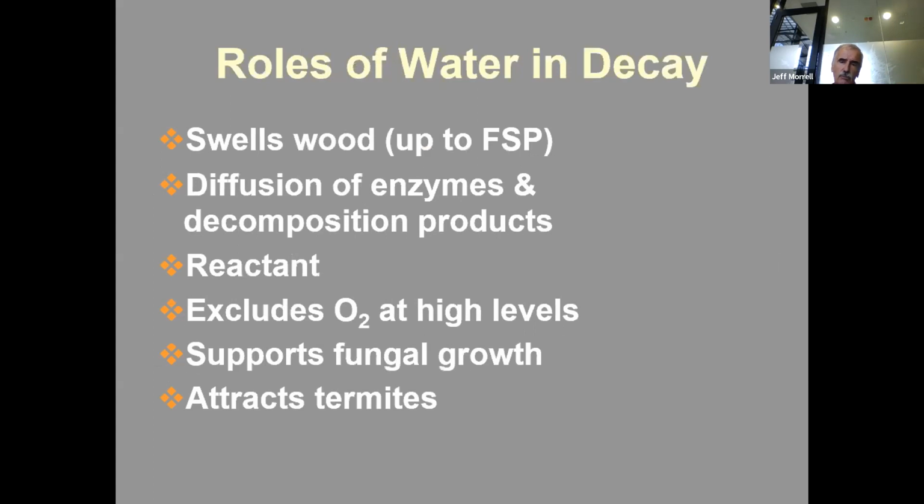So water plays a lot of roles in wood. For one thing, it swells, as we talked about. Up to the fiber saturation point, the wood will swell. It is really important to have free water for the fungus, because the fungus can't reach out and bite the wood and tear off bits of it and chew it out. It has to have moisture for the enzymes that it produces to diffuse into the wood and the breakdown products to diffuse back. So if that's not present, that doesn't happen.